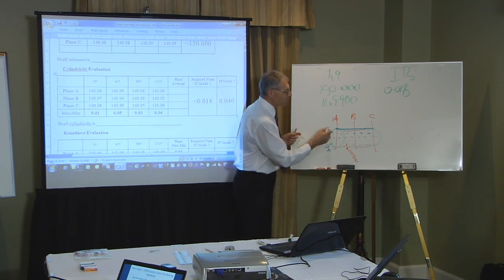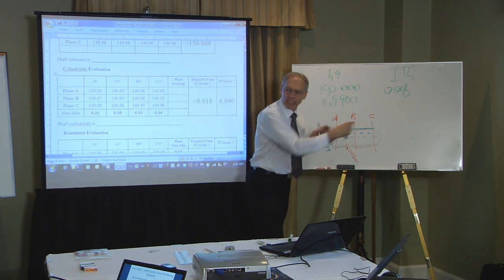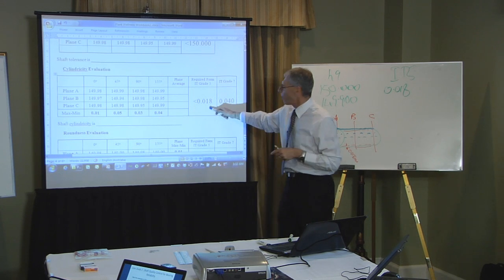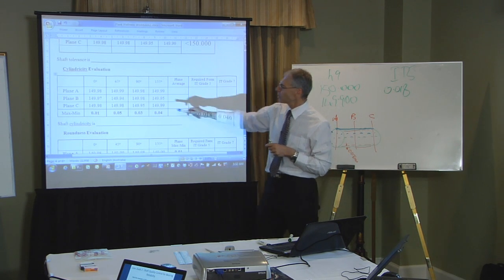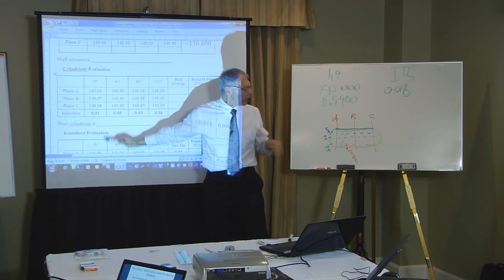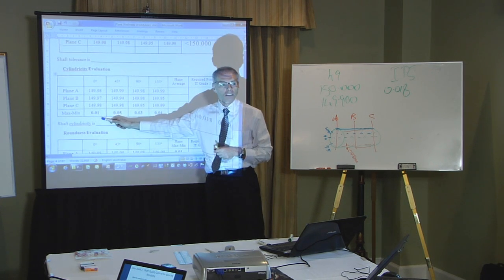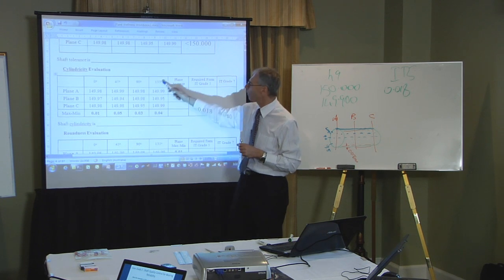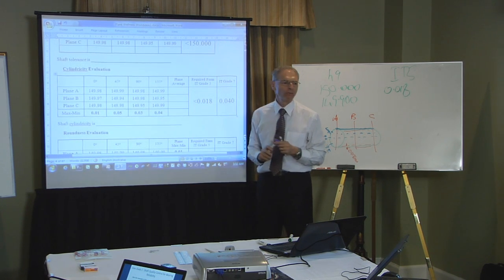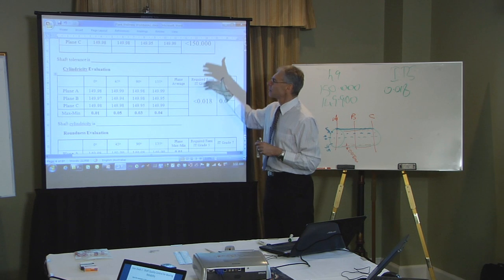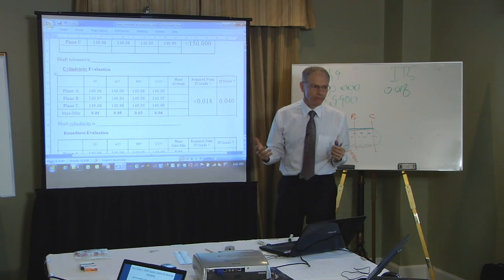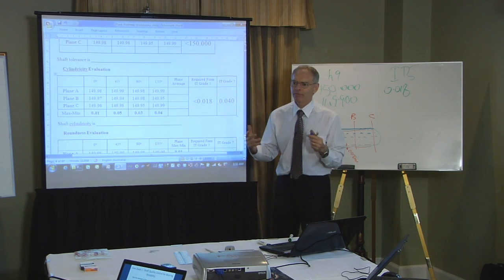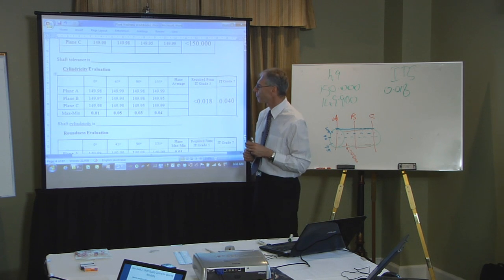So is it a cylinder? We're measuring along the cylinder in that case. It must be less than 18 microns. Along the 0 line across the top, yes, 10 microns meets requirements. At the 45, 50 microns, 90, 30 microns, 135, 40 microns. This shaft isn't a cylinder. It's not cylindrical enough to give full service life of that bearing.